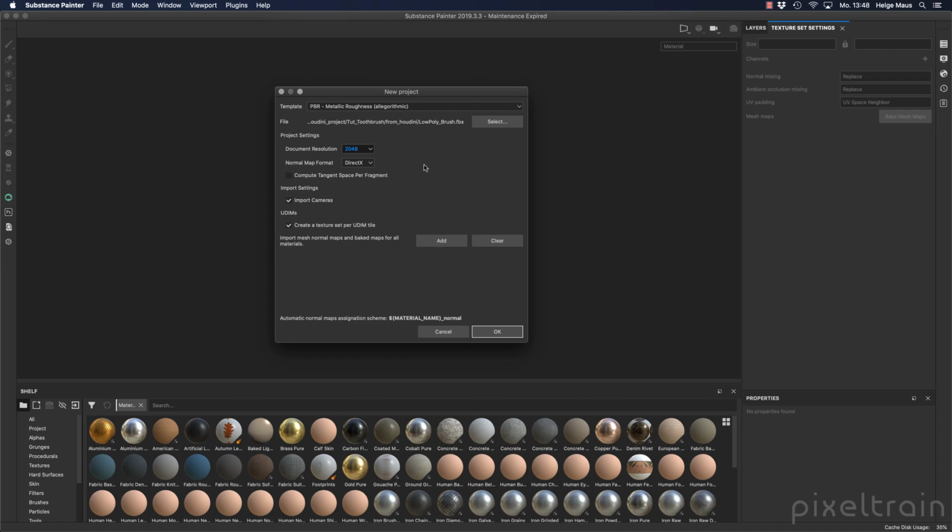And the cool thing is you can switch the resolution for every texture set, and for this document here, for example, only 1K. You can work with this if you need. For example, now in the viewport of Substance Painter, for one part a higher resolution, you can switch this in the texture set.